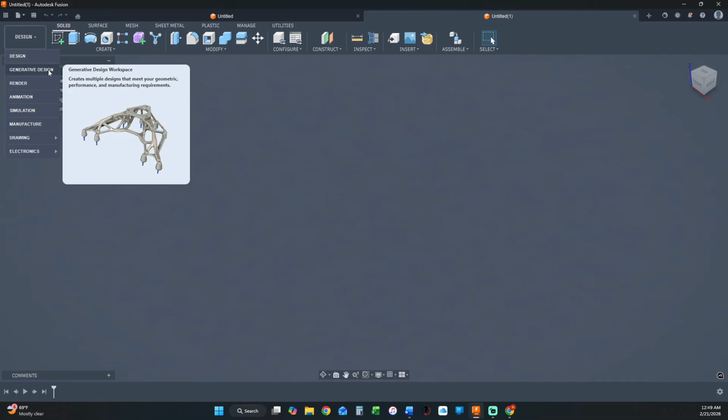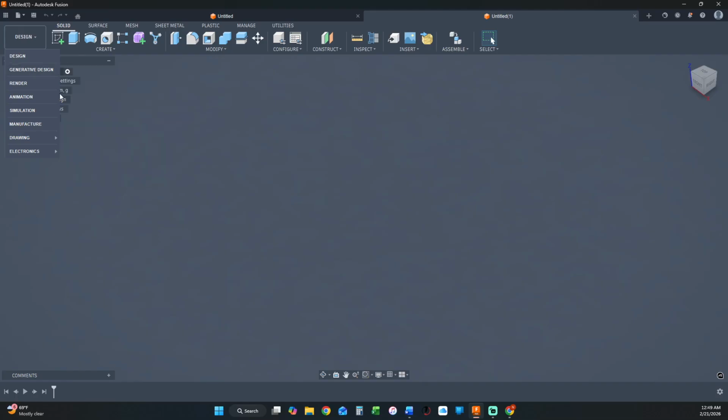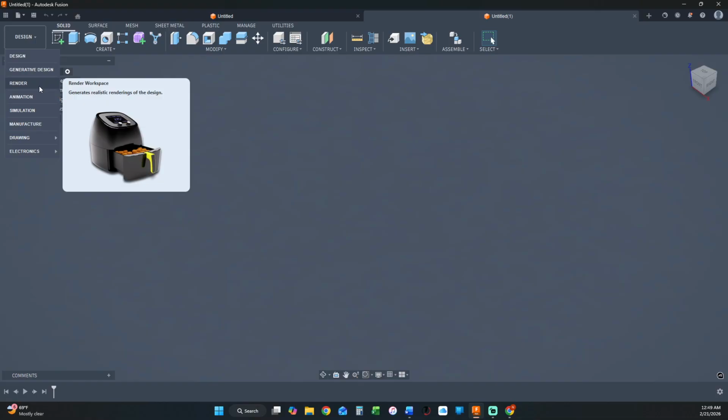Generative design, I've never seen this anywhere else. This is where if you have a part or maybe some known geometry that you need, and you know the loading, like what's shown here, you probably have to lay out this feature up here, and you know your mounting points down here, and you would input your known forces, whether they're thermal or mechanical or whatever that might be, and Fusion is going to use math and likely some FEA behind it of what's the best structure you can develop to create this, given all the constraints. That's generative design, and I know some car companies are using that now.